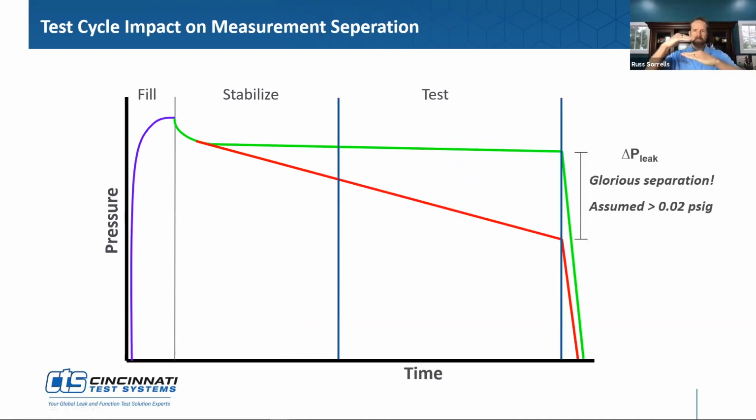Yeah, so the way I always explain that to customers visually, when we don't have the graphs in front of us, is imagine your tolerance window, your accept reject window, is here, and then you add more cycle time and you increase your accept reject window by adding the additional cycle time. So now it's much easier to hit this window than it is this window. So your repeatability, your gauge R&R, is going to be much improved as a result of expanding that out.